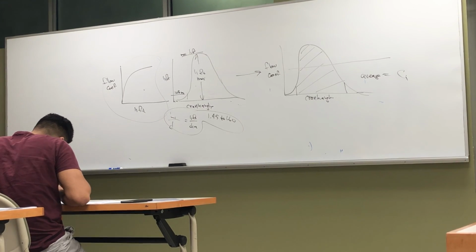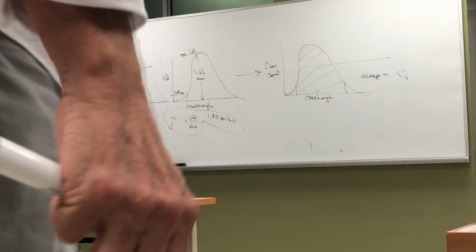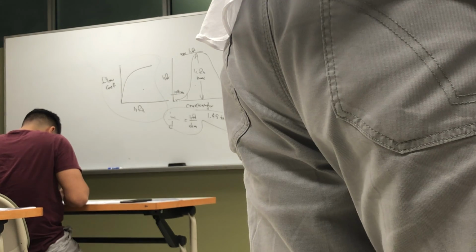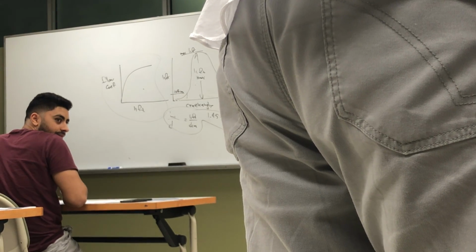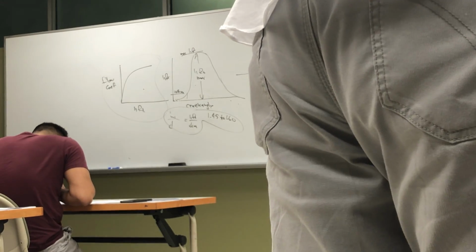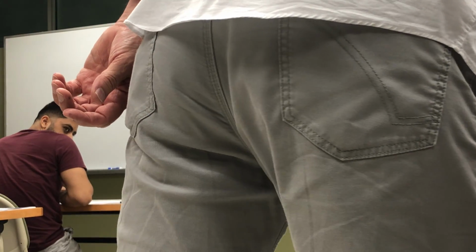See here, this is the proper area, in between this 10% lift to that 10% of max lift. And this one completely negates all of that. So this one's correct, and that's incorrect.